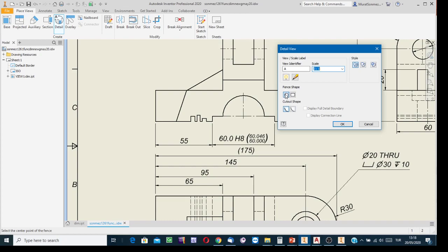We bound the regions with smooth circles, so select the circle fence option, not wavy but smooth fence. If there will be more than one detail view, joining the detail view and the region with straight joining lines is a good practice. A reader following the straight line can easily reach the corresponding detail view.